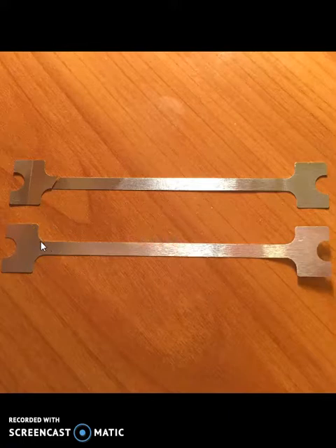So what we're going to do in our model is just look at the rectangular portion of the sample coupon, essentially where this fillet ends, this whole length, to where this next fillet starts. The reason for that is because the cross-sectional area here is quite a bit bigger than the cross-sectional area here. And so the force that's imposed on this sample coupon is really concentrated into this thinner region. So we're not going to worry so much about the elongation in this portion, at least for our simple ANSYS model.